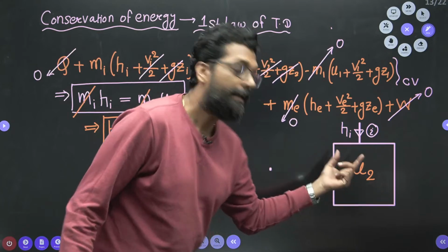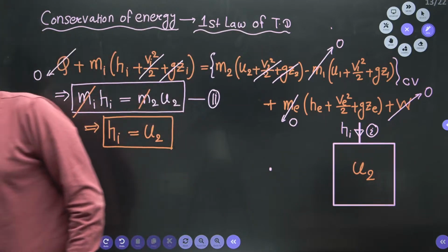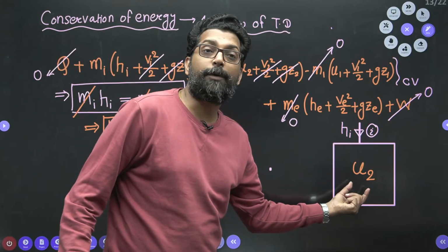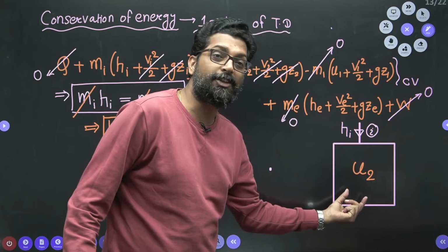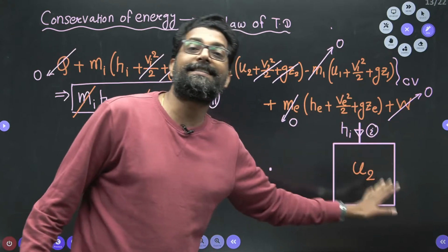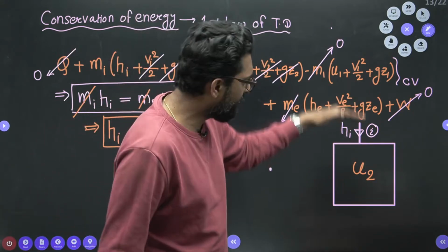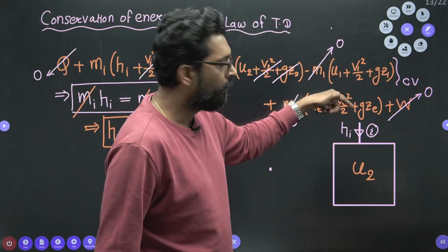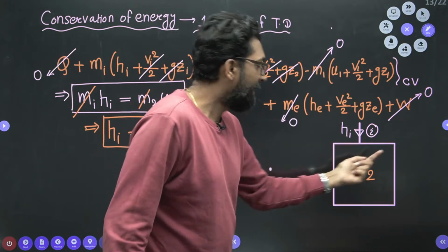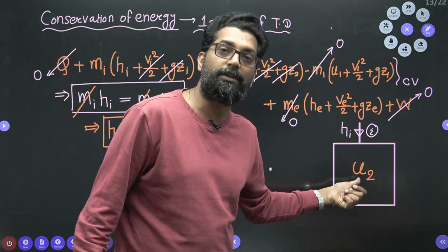When there is no change in kinetic and potential energy, no heat transfer, no work transfer, and initially the tank is evacuated. In that manner, the inlet enthalpy, which is the enthalpy carried in with the air at the entry, is equal to the final property of the tank for the air.